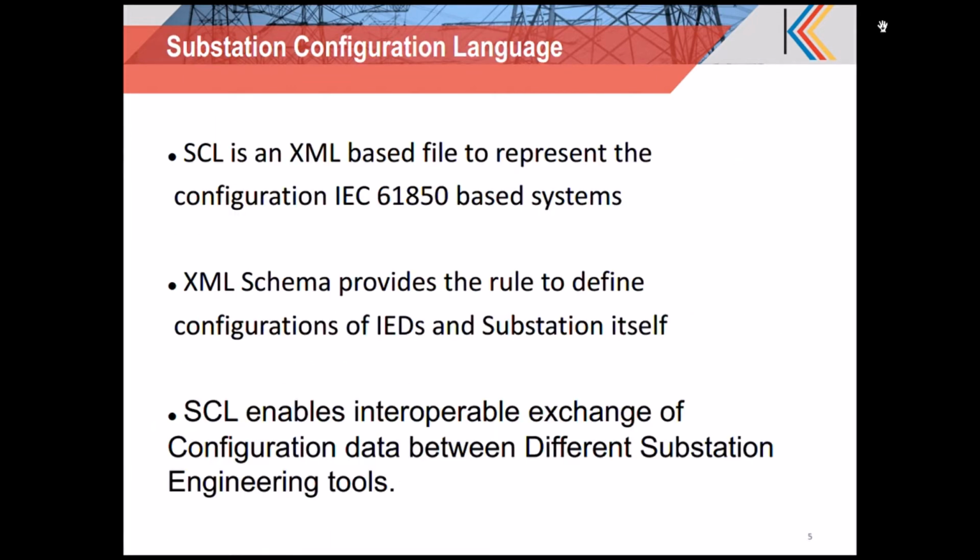Now moving on to the 61850 Substation Configuration Language, SCL. This is the basis of doing any configuration in any tool. All the tools we are talking about will be using this SCL, which is an XML-based representation of 61850, its models and its communication elements.